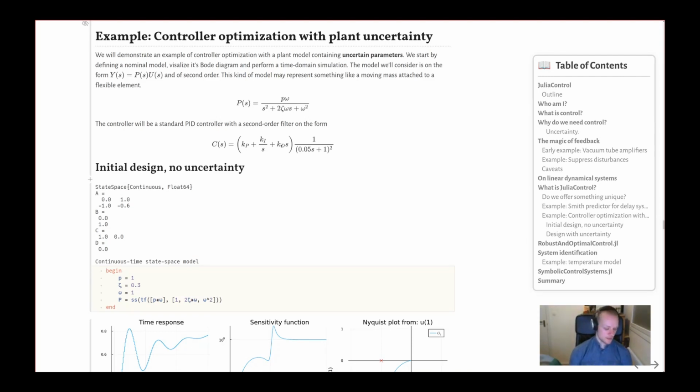So in the case of a robot, if you feed back measurements from an accelerometer, accelerometers are known to be very noisy, and if you differentiate that, you get an extremely noisy input, and that input is what you send to the motors of the robot. And if you have too much noise there, you will actually hear the motors start making a noise. They will get very warm and they will wear out prematurely. So filter design is critical when you design a control system also.